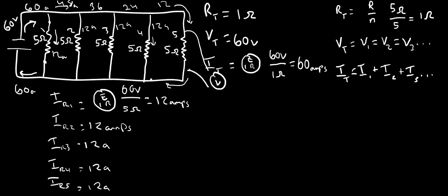This is what Kirchhoff's law is. It starts combining again. So 12 amps is coming down, combined with 12 amps here, and you get 24 amps along this leg. That's how you tell these amperages match, and that you're doing your calculations properly, because what is coming out of the circuit is going back into the circuit.